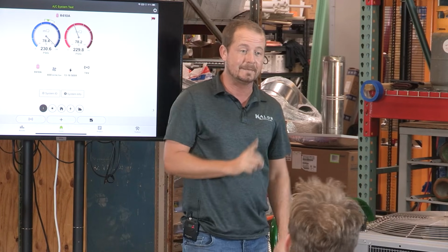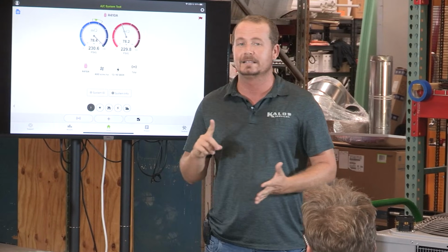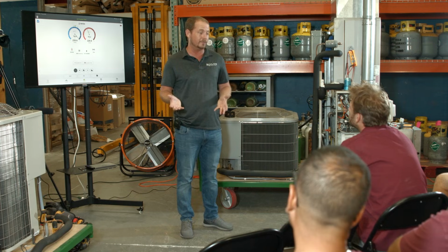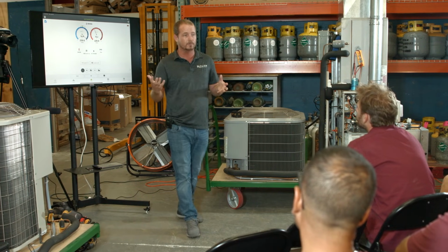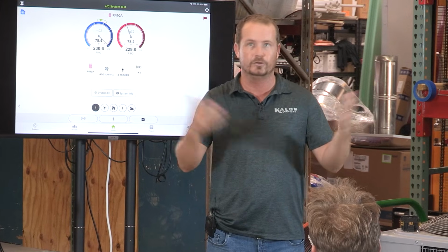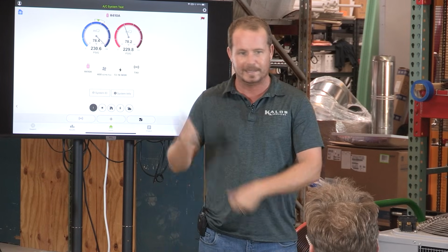So when I say stand behind it, I do not stand behind that as an airflow measurement tool, really, but as a qualitative, is a damper open or not? It's actually a great way of doing it. We used to work in these big custom homes in Isleworth and Windermere and all this, and you start up a zone damper system, or maybe two in a house, and you got to go through and make sure each damper opens and closes, and that's an excellent tool for that.